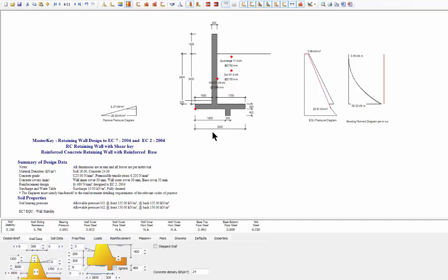The use of nibs is quite debatable. It depends on your passive soil, and it depends on the height of passive soil. The reason for that is that you're taking a loading here that's coming around 25 kilonewtons, and it's quite high. Maybe it's only 20 at this point, so it's 20 and 25, so that'll be about 22 average. Whereas on this side, your resistance is coming in at 28.